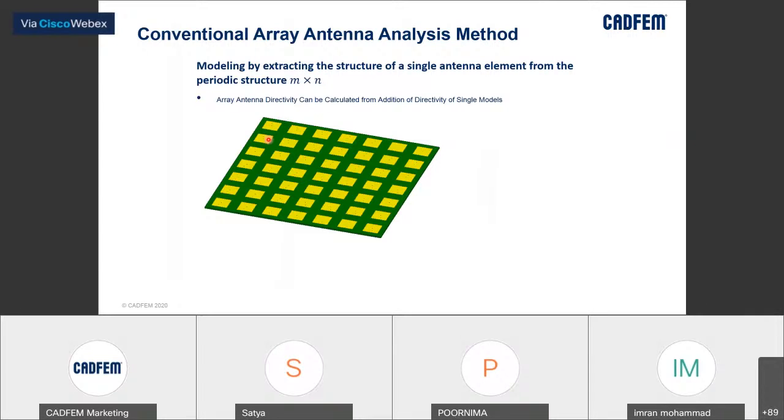But in the base station, there will be multiple arrays of antennas providing very high power and a high beam. If multiple signals are there, then due to constructive interference, it will bring out a very high directive beam. And depending on the interference and the phase of the different devices, the beam can be tilted.